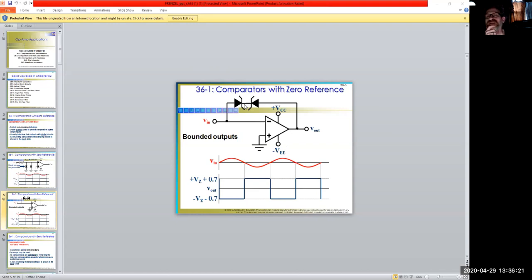They try to deal with any interference or noise, if you will. And so what becomes our output at this point? If you notice, it's 0.7 and 0.7 in this. That's because of the driving of the two different diodes tied into the loop like this. So it's a different way of controlling a comparator, a rather simple approach, if you were going for a specific response for a signal.